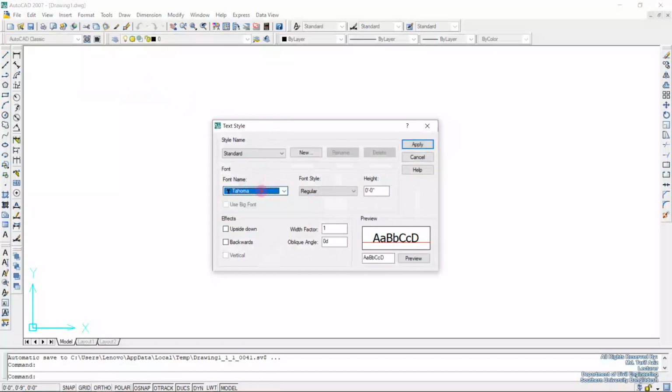So just press on there and press on T, then go to Times New Roman or other options, you can find it in there. And font style is regular, but you can choose other options. Again, height, so I want to provide a height of 8 inch. So this is it, just press on apply.